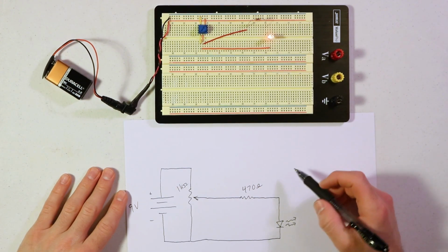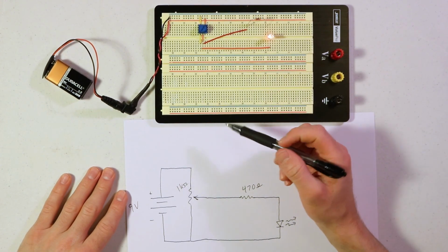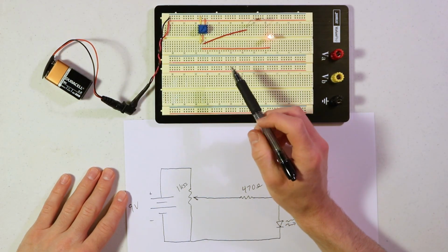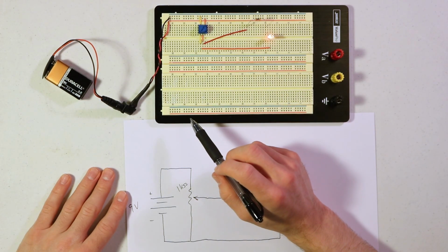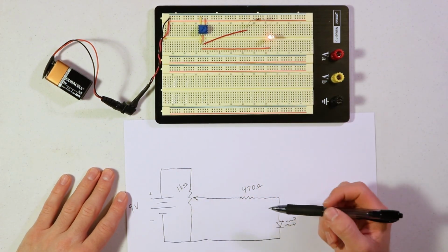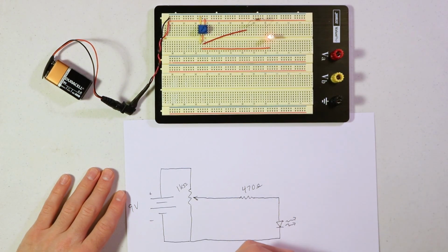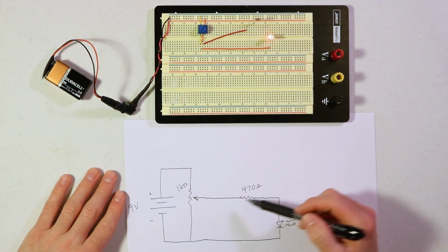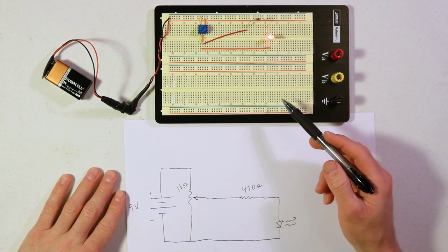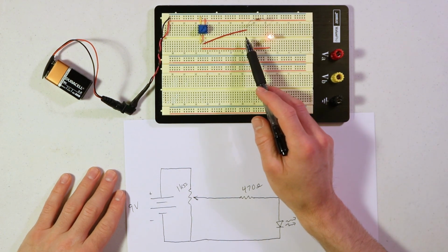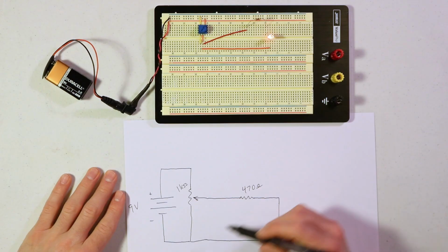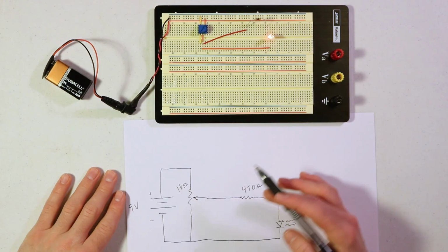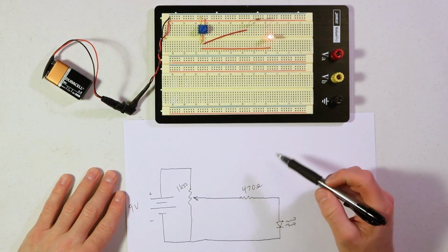So this is really all there is to it. When you build a circuit on a breadboard, you just figure out, the rows are connected, the power rails are connected, and then you just plug your components in and then connect wires between the components so that it completes the circuit. And then when you're drawing your circuit diagram, you can just have your power source, you just have all of these components, and then you just draw the lines that connect them just like the wires do on the breadboard. And I know some of these are diagonal. Normally when we draw circuit diagrams, we want to keep nice horizontal lines, but it's still the same layout, even though this diagram looks slightly different than this.